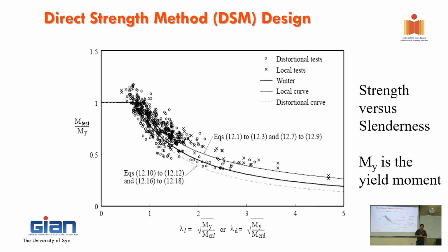Thousands of pounds are spent to build and design based on the curve, and if you bring the curve down, it means it's not economical, right? So you have to balance between the chance to get that and the chance to design for that. But anyway, it doesn't mean that it's not safe. It's actually safe because it has been covered by the load factor already, the phi factor. So it's no problem. Just giving you some insight behind that.